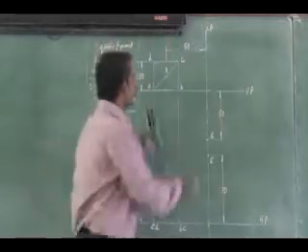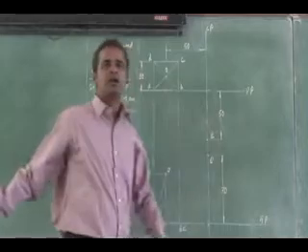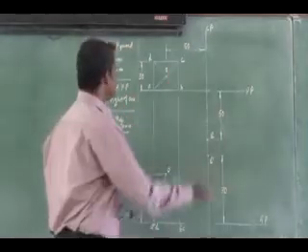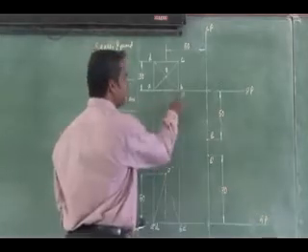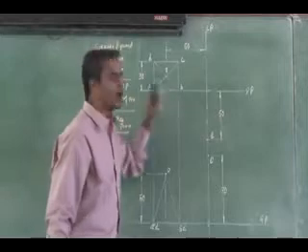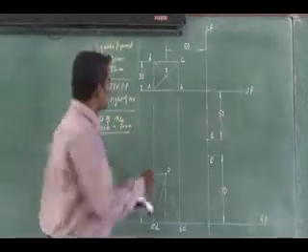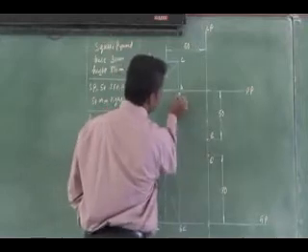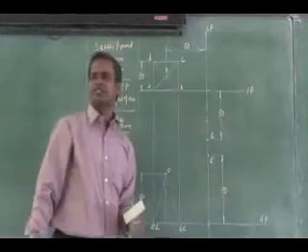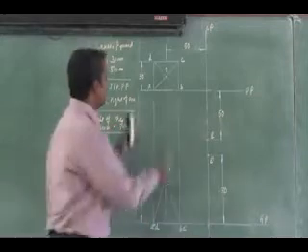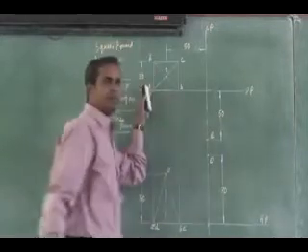Then you try to get the intercept of all the corners, including the apex. So you see here, what is the intercept of A and B? If I join it to station point E with a visual ray line, wherever it intersects the picture plane, that is the intercept.